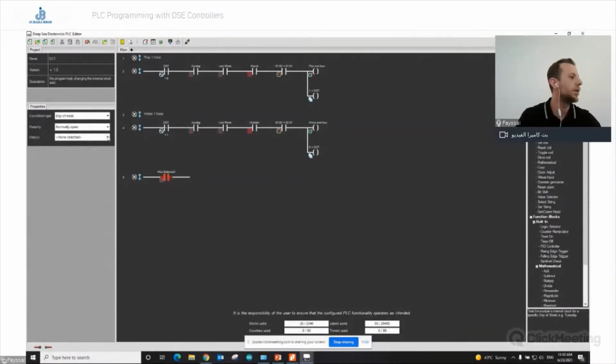condition. So I'll go to days. I'll say Sunday. Then I'll go to week in a month. I'll put it in series because I need an AND function. I want to make sure that when it's Sunday and it's the last week of the month and it's March, and the time is as such, I'm gonna drive certain coils. So let's see how this happens. I'm gonna select my week. I'm gonna say it's the last week of the month.